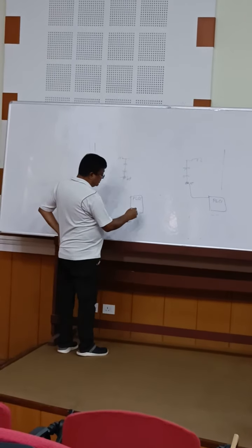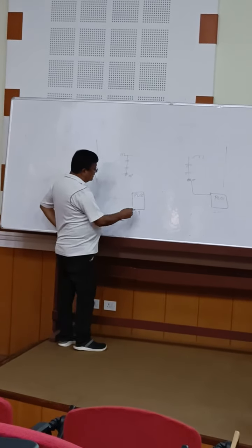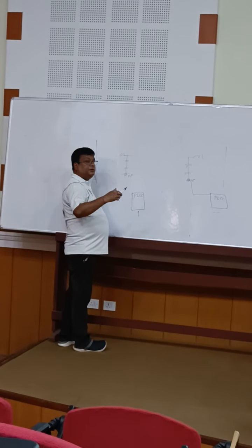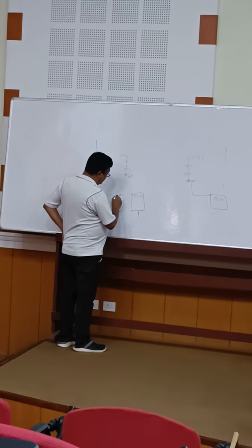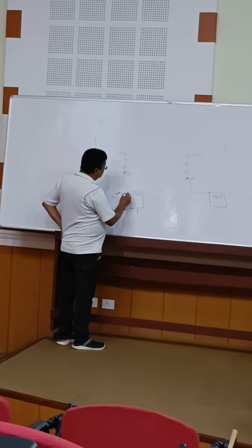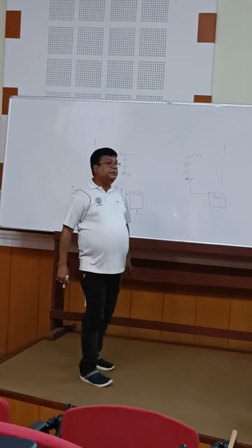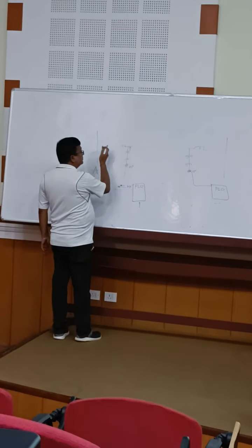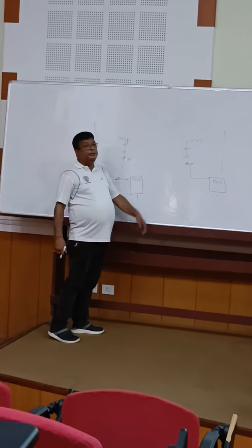So someone speaks, voice communication is there. So this power line carrier communication, here it is modulated, and the carrier will be added. That will transfer the signal. So after modulation, this signal will be added with the carrier signal, so it is a high frequency signal. This will travel through the CVT because CVT is a low impedance path for the high frequency. So once it lands up here, we do not intend that it should go to the substation. It should go to the other end.